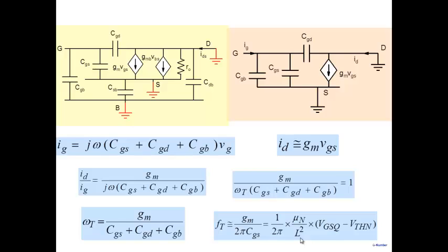And that sort of explains, if you look at the evolution of the entire electronics, a constant trend has been that almost every year and a half or every 2 years, you will find that the channel length of the MOSFET is shrunk by a certain factor. And there's been a constant effort over the last 30, 40 years to shrink the channel length for 2 reasons. One is, as you shrink the channel length, your MOSFET becomes faster.